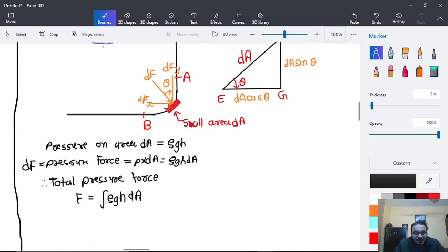Now there are many strips like this. So if we are near to B, then the strips are getting changed everywhere like this. And here the force direction will keep on changing. If you see, the normal force will have different direction for each strip. So this integration cannot be done directly, so we will have the Fx component and Fy component everywhere.